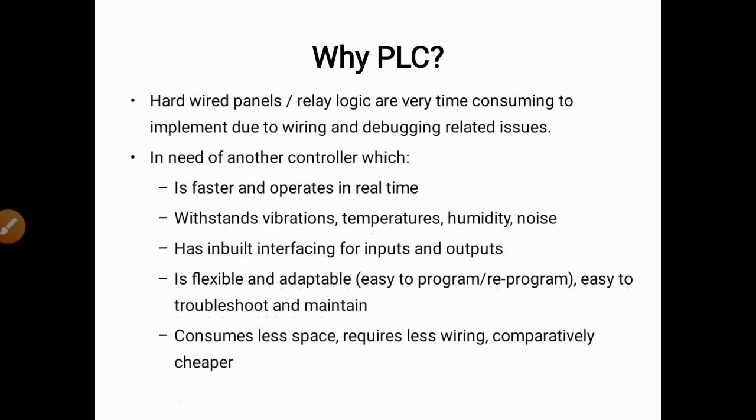Because of all these issues, there is a need of another controller which is faster and operates in real time, which can withstand vibrations, temperatures, humidity and noise. It has inbuilt interfacing for input and output, with interfacing that is flexible and adaptable, easy to program and reprogram, easy to troubleshoot and maintain. It consumes less space, requires less wiring, and is comparatively cheaper. These are all the needs which are fulfilled by PLC. PLC is fulfilling all these requirements. That's why we are now using PLC.